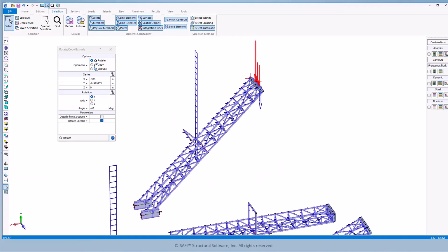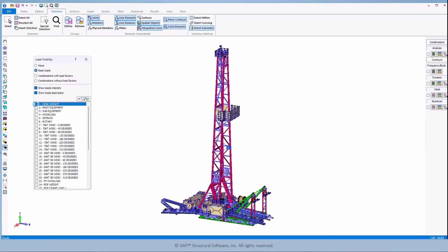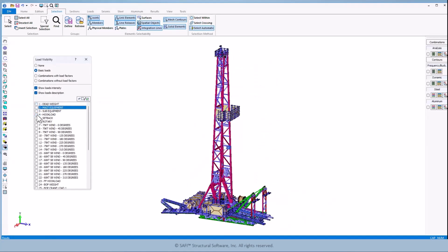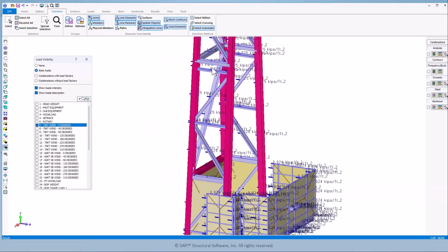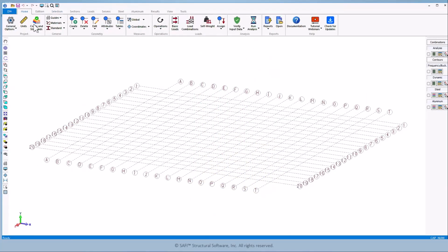Another of PSE's powerful features is its automated wind load generation. Based on the wind directions and parameters you activate, the software automatically calculates and applies wind loads to every structural member, fully in accordance with API 4F 5th edition requirements. Beyond wind, PSE gives you full flexibility to define as many additional load cases as your project requires, dead loads, live loads, equipment loads, and more, and apply them wherever needed throughout the model, whether on individual members, joints, or surfaces. Let's now walk through building a very simple model from scratch.